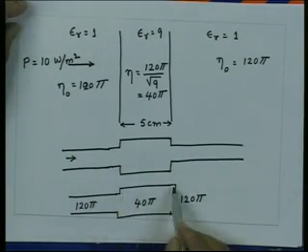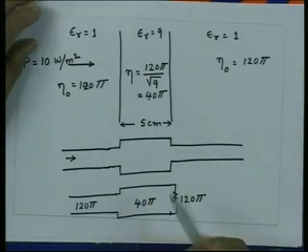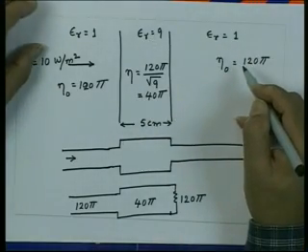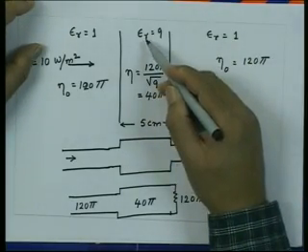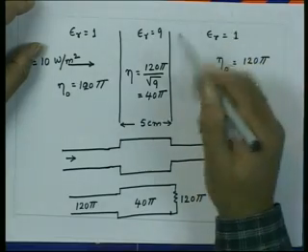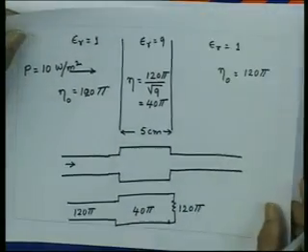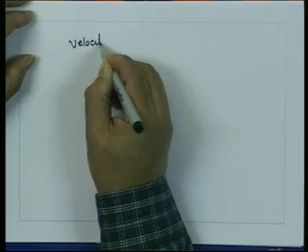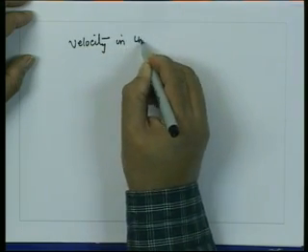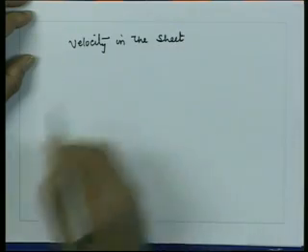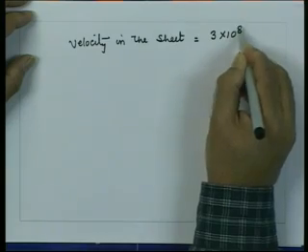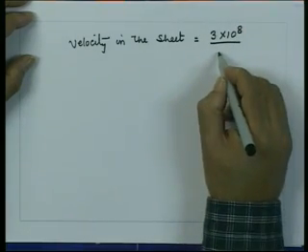For this we have to find out this length, which is 5 centimeter, in terms of the wavelength, and the wavelength depends upon the dielectric constant of the medium. So, here we can calculate the velocity, and from there the wavelength of the wave in that medium. Since epsilon r is 9, the velocity of the wave in that medium on the sheet is equal to the velocity in the air divided by the square root of epsilon r, which is root of 9.